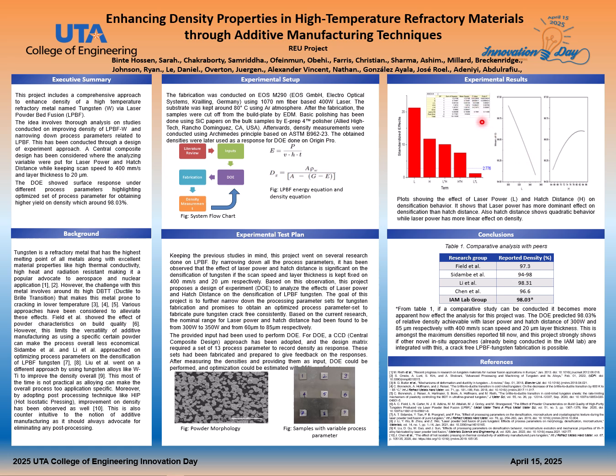From the table, as we can see here, the laser power has the most effect on the density, then the hatch distance, and then the other quadratic effects. Ignoring these for now, our only concern is the laser power and hatch distance. As we can see, the lower the laser power is, the higher the density will be.